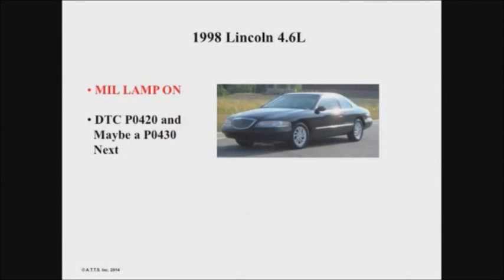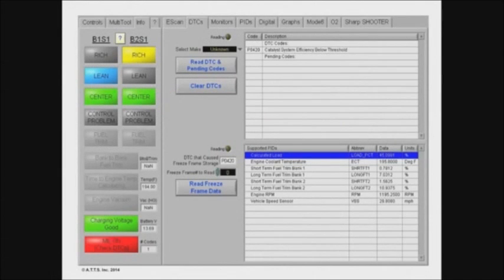Here we got a 420 and 430. And we can see, there's the 420 first. We have fuel trim, long-term 7% and 10%. That's up there, correct? And if you got both banks, you see my both banks now? Look at one that's at 61%, one's at 36%. It's a Ford. Where are you going to go? What do you think could be the problem?